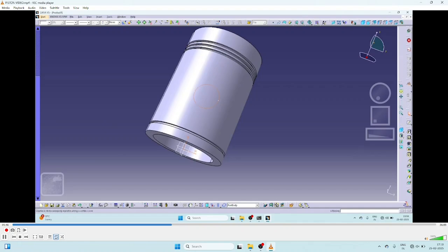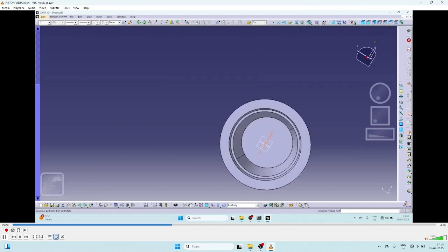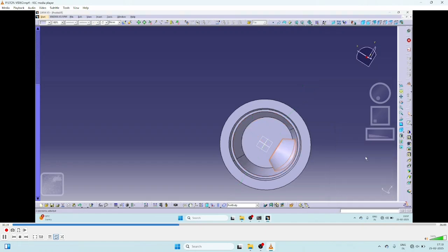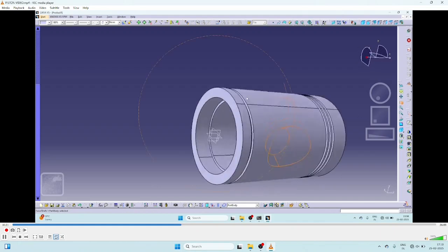Now it is at the middle plane actually. You can see the object, it is on the middle plane circle. So drafted filleted pad, length equal to -30, that is some shifting, offsetting. Select the reference surface as a shaft surface. Need not require any fillets, so cancel the fillets. Angle equal to 30, draft angle equal to 30. So you get these objects.